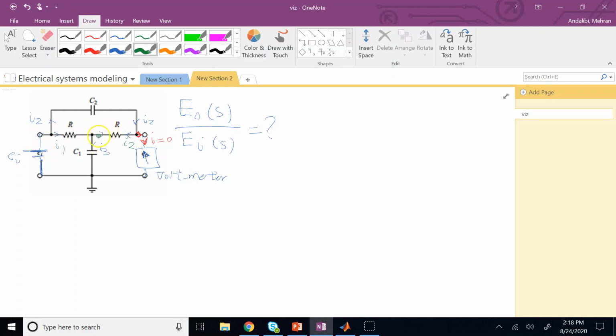Right, so this one here, I can basically draw it backwards instead of this way. I can draw it this way. And clearly this is the same as what? I2. So it's not a new variable, I4. So I1 here comes in, I2 comes in, and I3 goes out. So one of the important things is do not create a new variable if it's not needed, because then you have to come up with another equation to eliminate it.